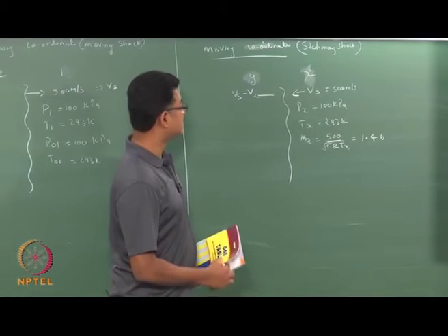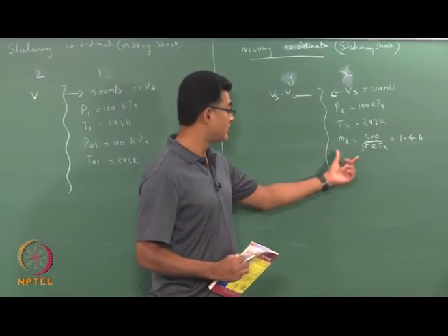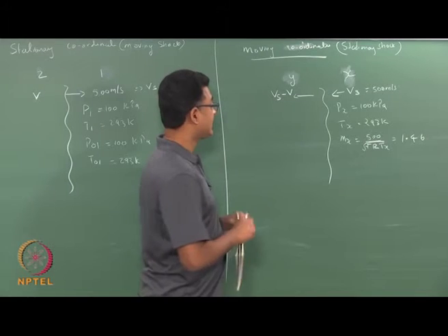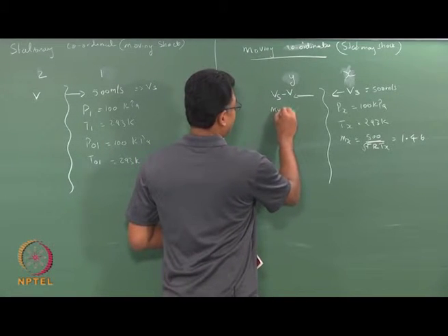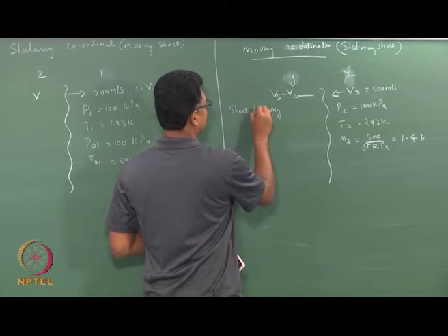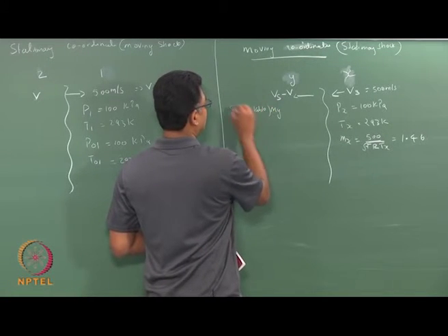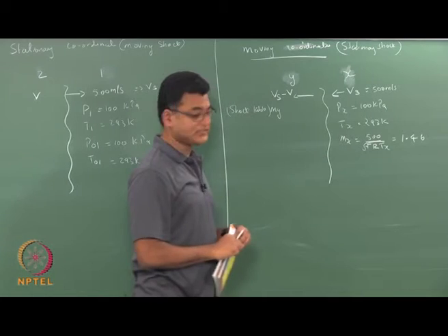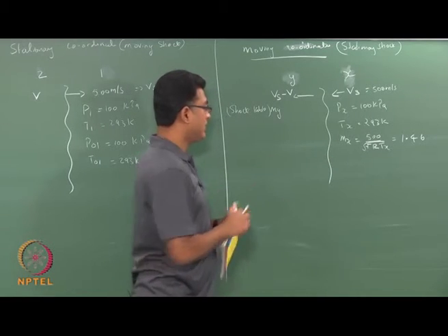Okay. So this is a stationary shock wave. So now I know my Mx, from which I can find my My from shock tables. Because now the shock wave is stationary, I can use the shock wave tables.